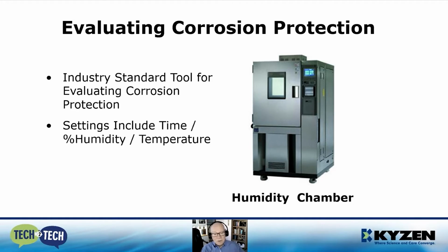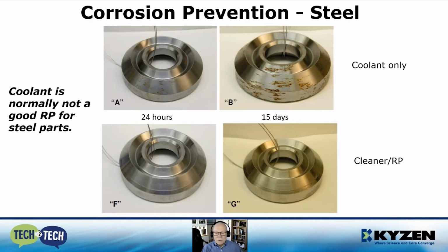And we can determine very quickly whether or not particular parts will have 90 days protection or even longer in actual practice in the field. The settings are time, temperature, and humidity for one of these chambers. And just about all of the large OEM automotive customers, for example, have their own specs on the humidity chamber.